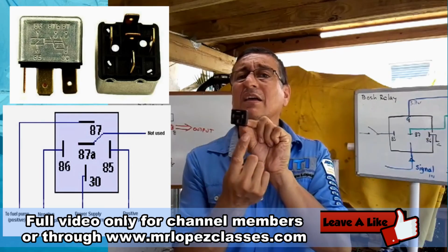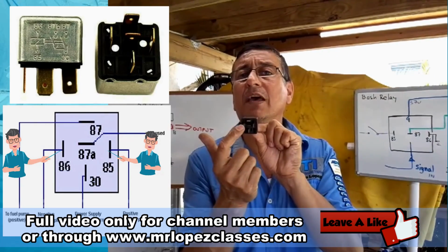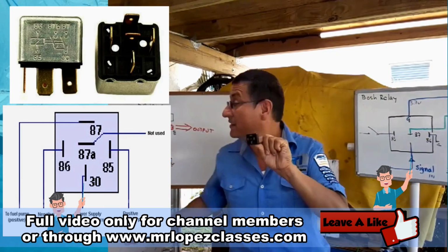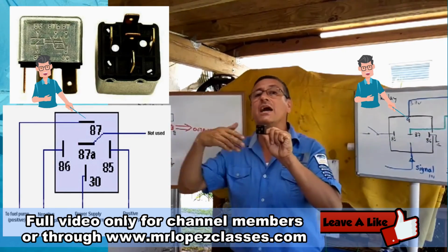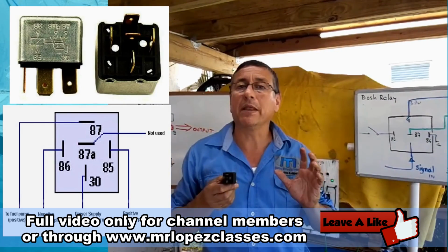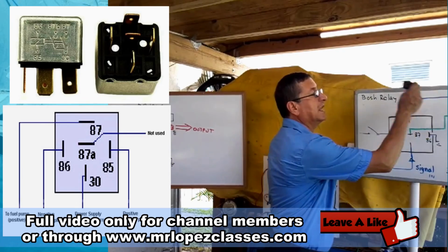This is the coil. The nomenclature for the coil terminals is 85 and 86. 85 and 86 for the coil. And this is the input signal that I want. And this one on top should be the output signal that I want to send. In between this terminal and this terminal on top, the connection is normally open. When I don't have power between 85 and 86, those terminals are open. When I power it, those terminals close and the light is on.